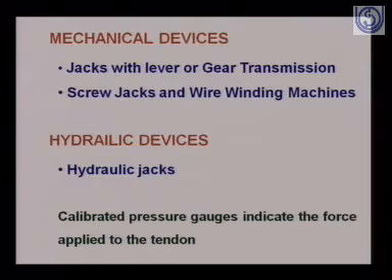So these strands are stretched, or stresses are generated in these strands, and these stresses generated in the strand thereby generate stresses in the structural member. It passes its stresses to the structural member, and of course an opposite nature of stress is produced in the structural member, because these strands will be in tension, so compressive stresses will be generated in the structural member.